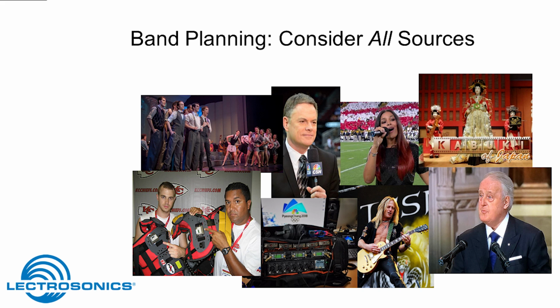Another very important thing to remember with band planning is to consider all RF sources. Can't tell you how many times I have been in a place where they've done the wireless microphones and maybe the comms, but they forget about the in-ear monitors because they don't somehow make the connection that it's all part of the same spectrum. Doesn't matter which direction it's going, either from backstage to the band or from the band to the backstage. It's all spectrum that needs to be shared between all these units.